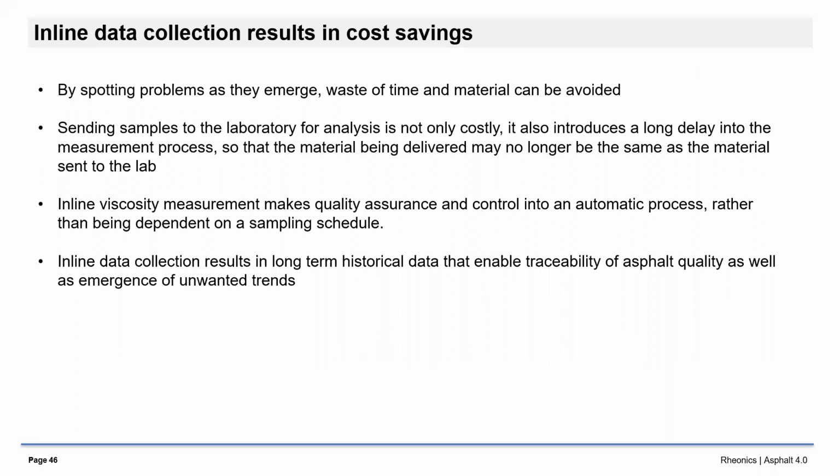What we have seen is that we have some sensors which have been installed for a couple of years now. During general operation, when you have water flowing through and maybe there is a shutdown and then they reheat the line and start operating again, we have never seen the need to take out the sensor and clean it. And as Joe mentioned, this sensor has a fouling detector, and in those cases we have never seen even the fouling detector warning the operator.